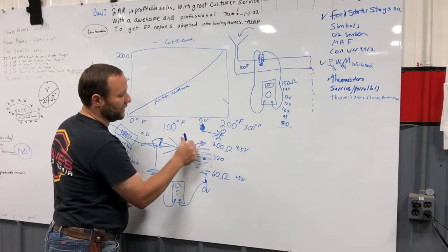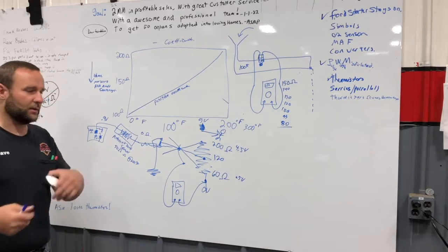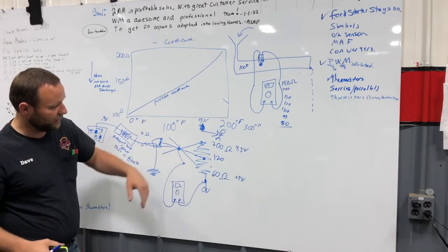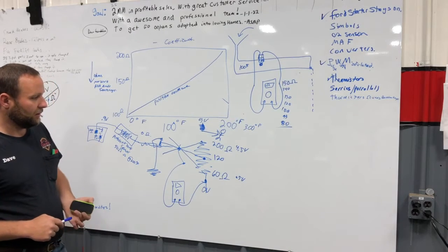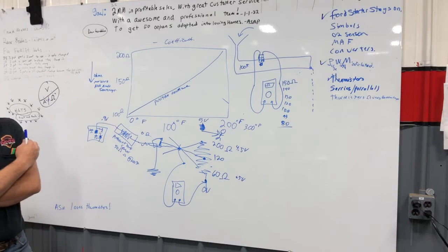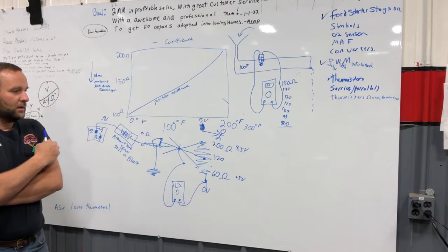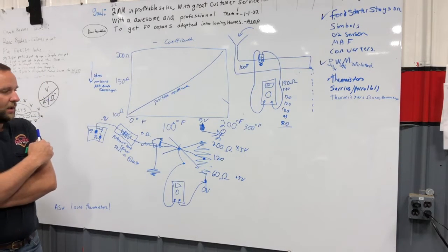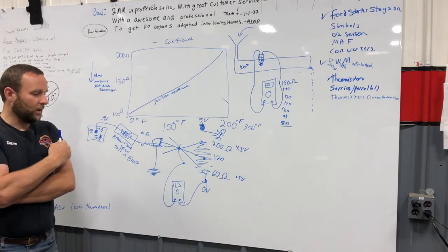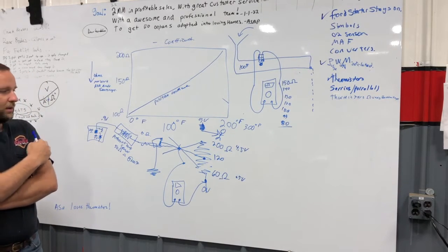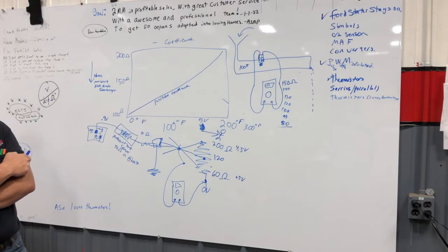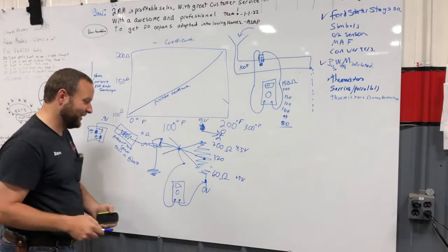Let's say we disconnect the car. So we're just talking about the fuel level sensor here. What's the spec? What's the range? Maximum possible range. 60 to 120 or 60 to 200? Okay, so let's say the car we thought had half fuel in it. What would we expect? Like 120. Ohms or volts? I would guess ohms.